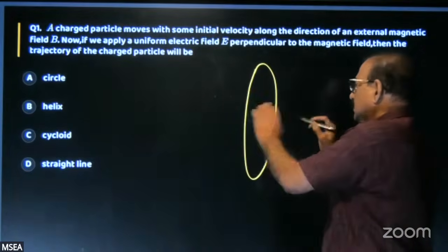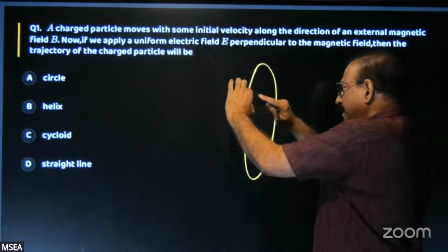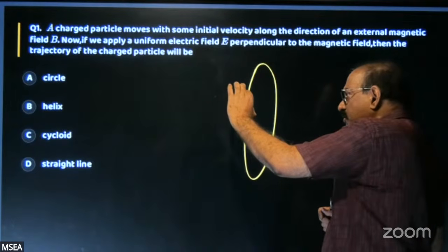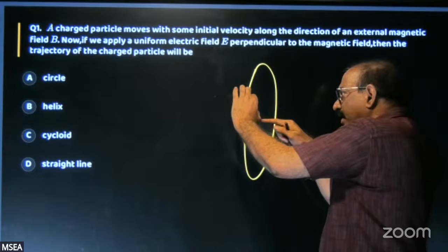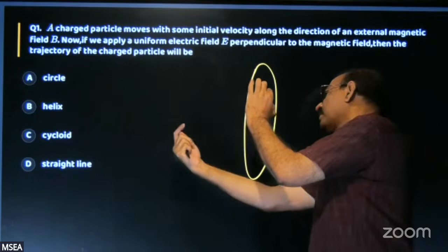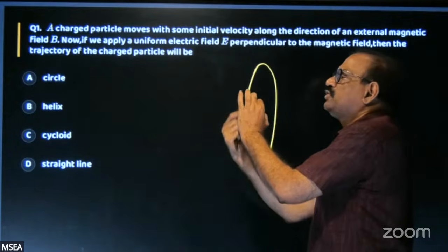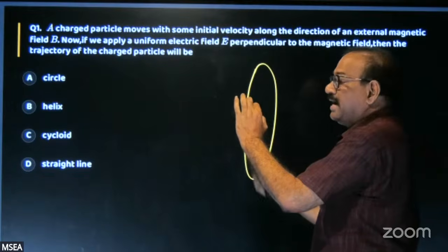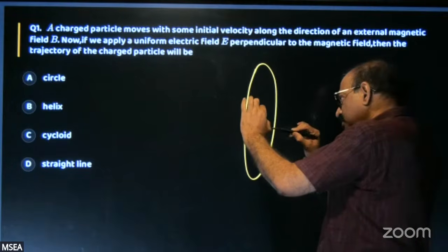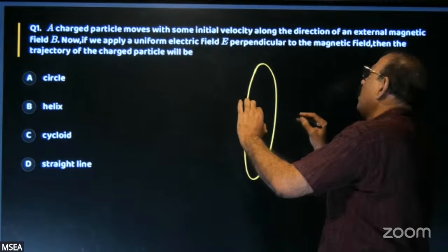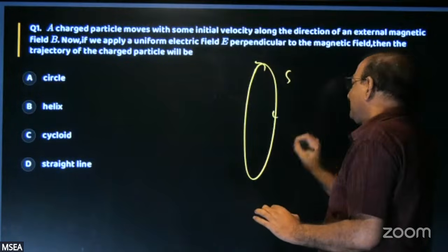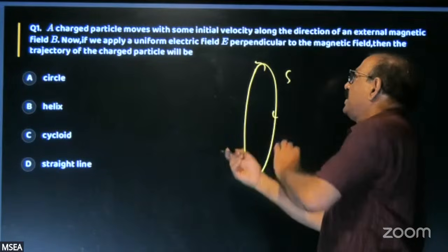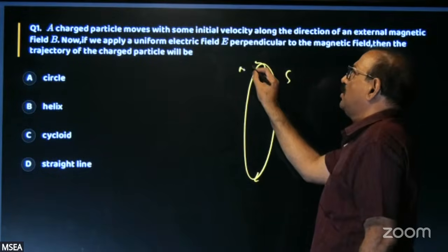No? Like that, there is a coil here. It is carrying current. If I look into this from this side, it appears to be carrying current clockwise. The same coil from the back side, if I see, appears to be carrying current in anti-clockwise. Whichever face appears to carry current clockwise, that will act as south. And the back side, rear side, will act as north.